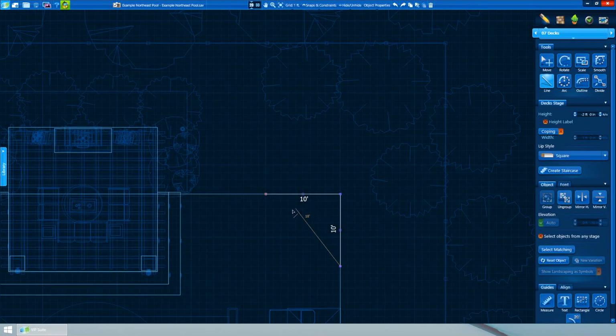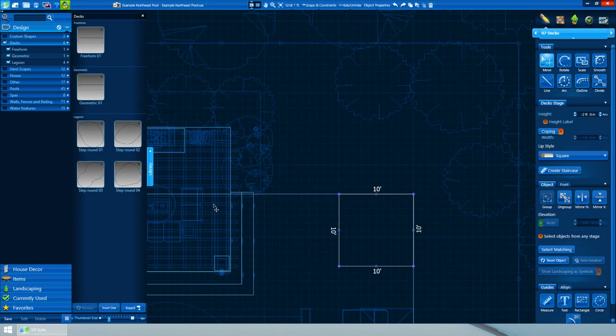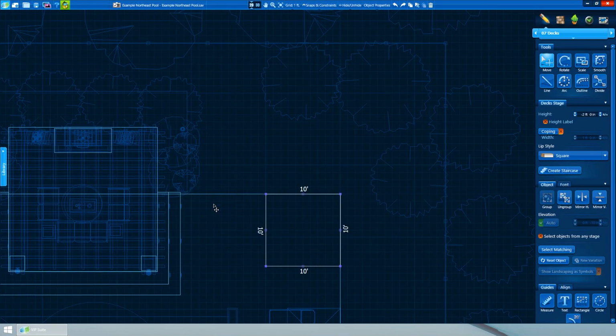Several new keyboard shortcuts have been added. While holding down the Shift key on the keyboard, World Angle will be activated to ensure our lines are kept straight. We can now quickly open and close the library with Ctrl-L. And finally, we can toggle between no measurements and selected measurements under Hide on Hide using Ctrl-M.